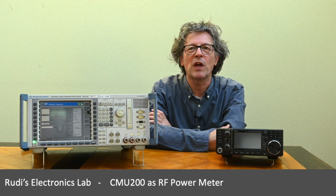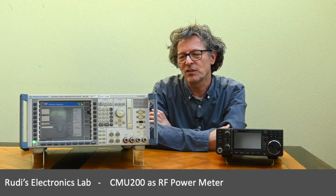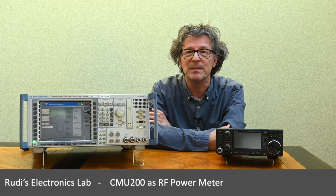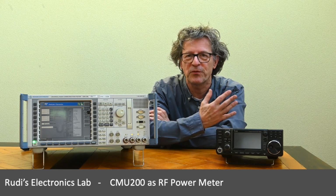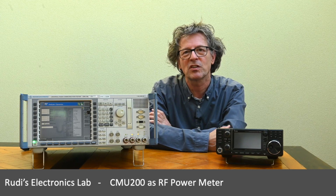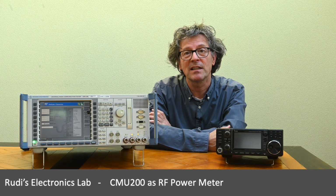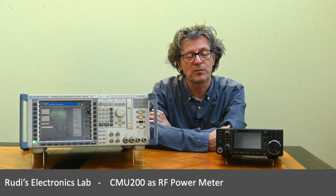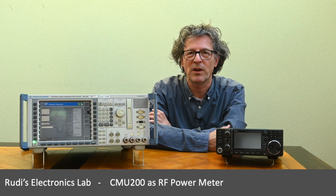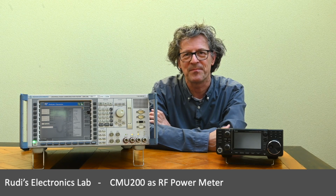Can you directly compare it to the high-end instruments that I showed in the beginning of this video? No, I don't think that will be fair. It doesn't have the precision of those instruments that are often way below 0.5 dB. It doesn't have the frequency range up to 50 or 100 gigahertz or something. It doesn't have some of the very specialized features that come with these devices. It doesn't have the dynamic range that we see in some of these professional high-end devices. But nevertheless, I think it is very interesting to have this functionality on the CMU, and I hope this video was useful for you in some way.